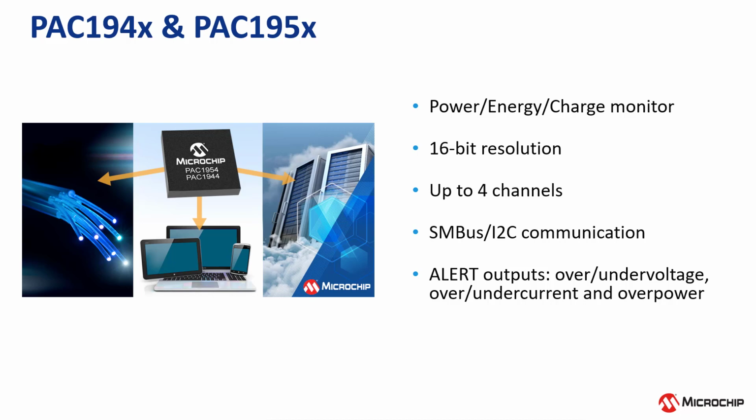PAC194 and PAC195 are power monitor device families with up to 4 channels, with current sense amplifiers and bus voltage monitors that feed high-resolution ADCs. Digital circuitry performs power calculations and energy accumulation. This enables energy monitoring with integration periods up to 1 year or longer.